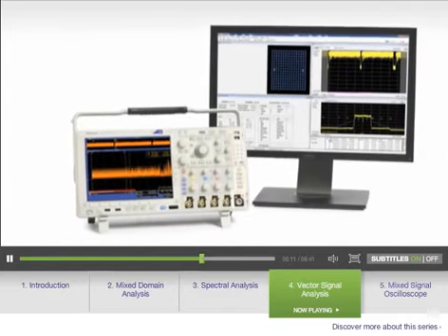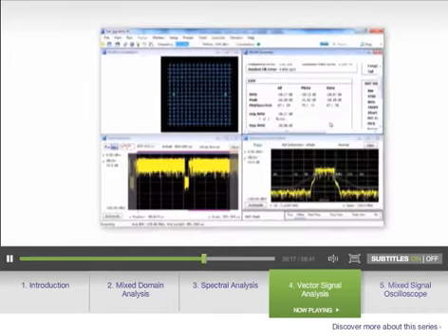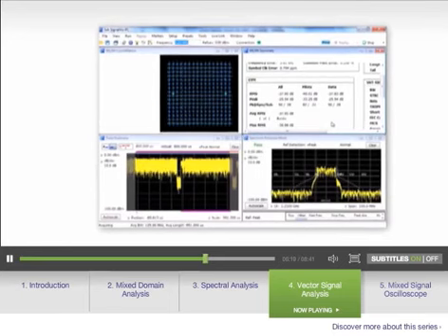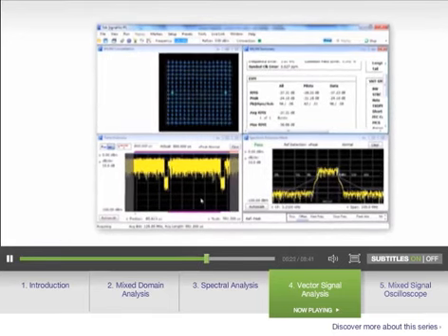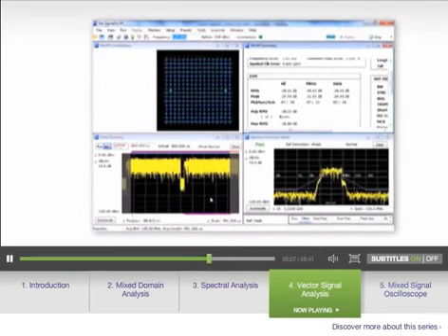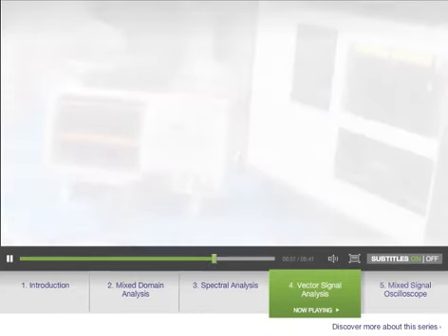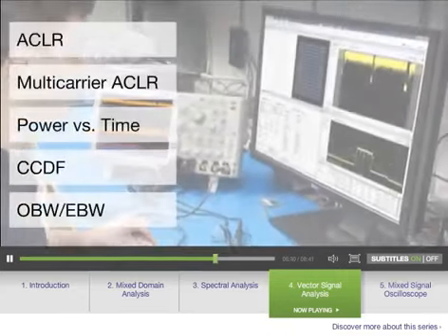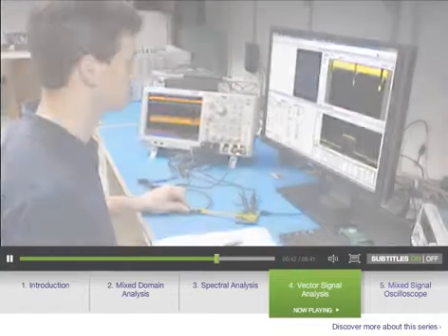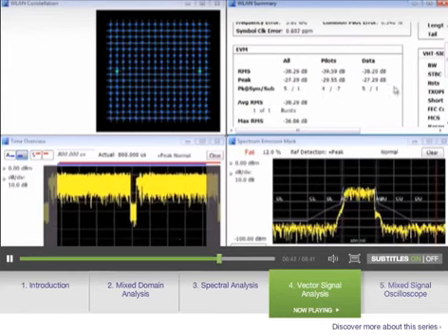Because the MDO4000B can capture more than 1 GHz bandwidth without sweeping, you can perform simultaneous spectrum, time, and modulation measurements even on wide bandwidth signals, such as 160 MHz wide 802.11 AC signals. Markers let you cross-correlate spectrum information, timing information, demodulation, and symbols. Power measurements and signal statistics help you characterize RF system performance. Measurements update continuously for a dynamic view of your system.